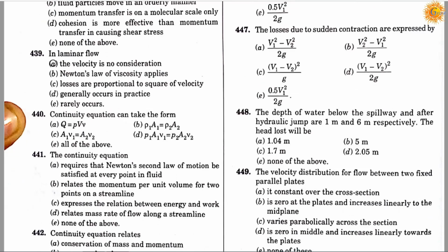439. In laminar flow, option A, the velocity is no consideration. Option B, Newton's law of viscosity applies. Option C, losses are proportional to square of velocity. Option D, generally occurs in practice, and option E is rarely occurs. So correct answer is B, Newton's law of viscosity applies.